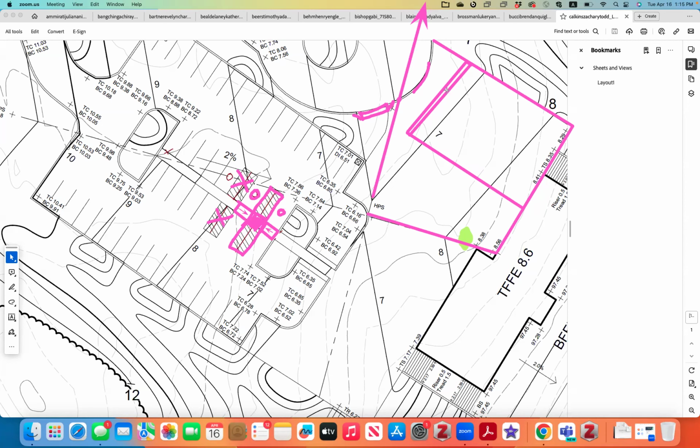Some sort of cutoff along the swale. No, you don't, water will just keep flowing down there. Yeah, it's this direction. The curb cut should be over there, on the lower side. Okay.